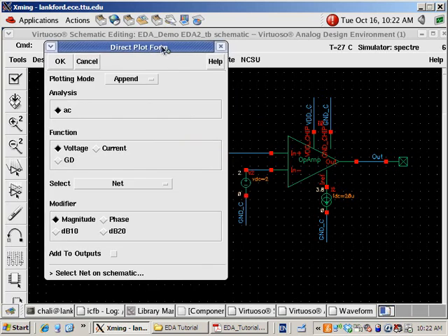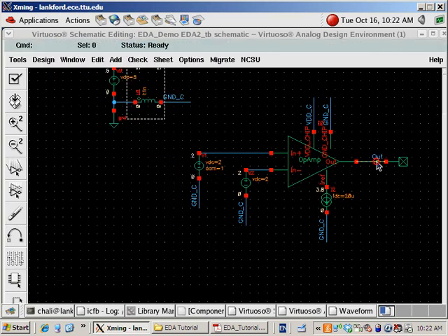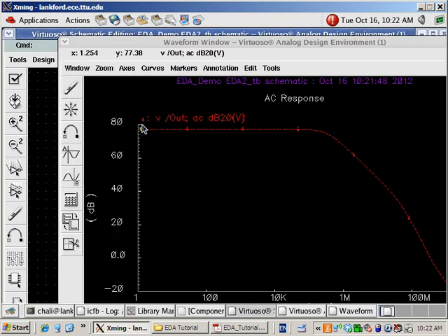From there, we can plot the AC voltage and convert it using the dB20 operation to calculate the dB scale gain. So if I click the output, we plot the output AC voltage and convert it using dB20. I click this, and now this is the result.